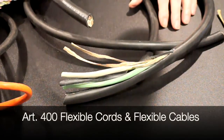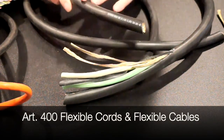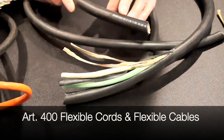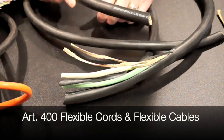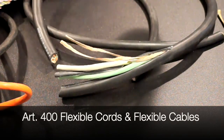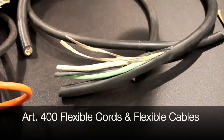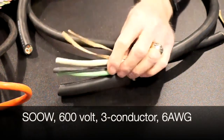So this is the first flexible cord that we'll take a look at. The first thing we might notice is on the outer jacket, there are some markings. Those are required to be there by the code, and it tells us specifically what those markings must be. And it tells us they have to be there every 24 inches. Now, that's a little hard for you to read, so I'll read what I can on the flexible cable back here on the outer jacket. It gives me the manufacturer's name, and then it says cord, 3 conductor 6 AWG.